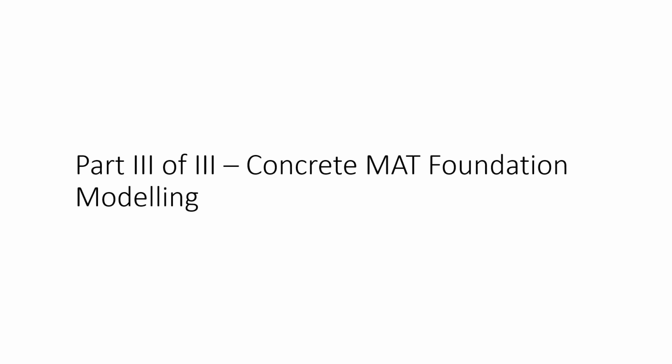The third part is going to concentrate on the design of the concrete mat foundation. And we're going to take a look at how seed files and groupings together can make your design process a lot more efficient. So if you have new people joining your project, they don't have to explore a lot of things. They have well documented seed files, a consistent naming convention for all the loadings and load combinations, so you can check their work and they can communicate with you as well.